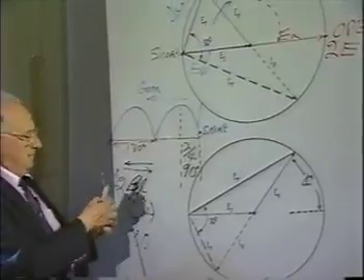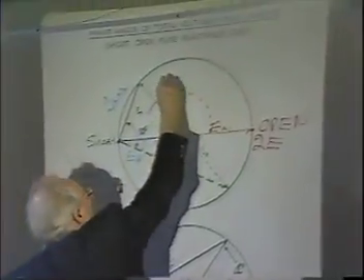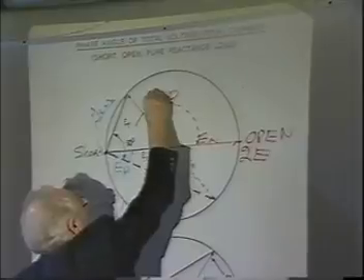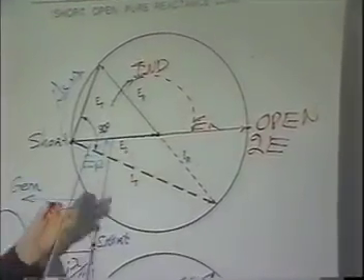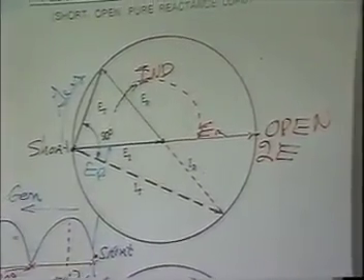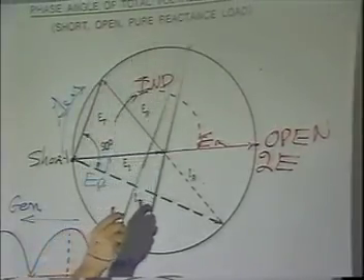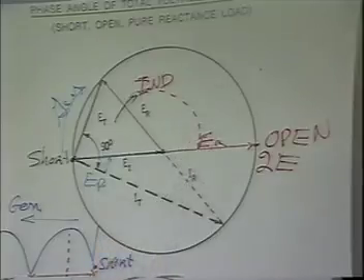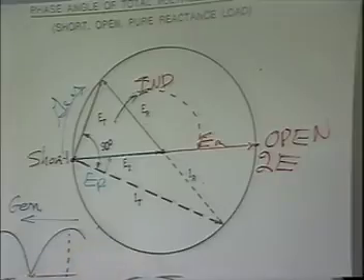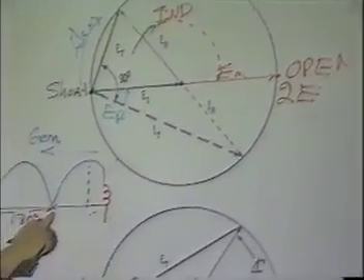It turns out then this side of the chart up here represents inductance. Therefore, what type of inductance would this be around this point here? Pure inductance. Total reflected voltage, right? Now what that means is that if I take the short circuit away and I put the right value of pure inductance here, I didn't even change this minimum, did I?